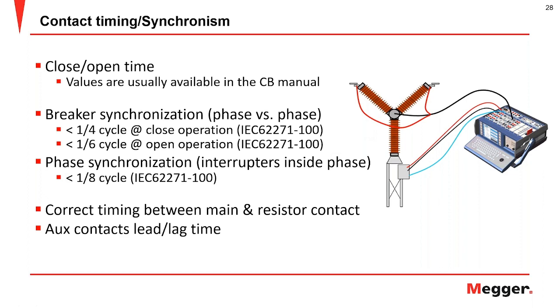And of course, the instrument will have to measure the correct timing between the main and resistor contact if they are installed, and simultaneously timing the auxiliary contacts lead or lag time.